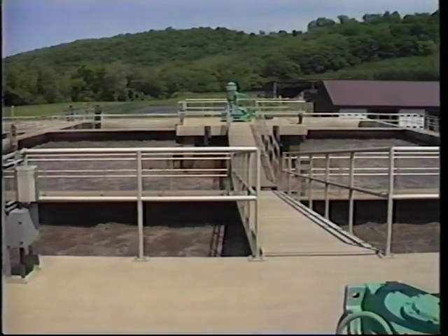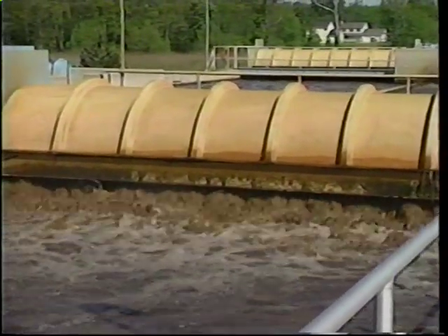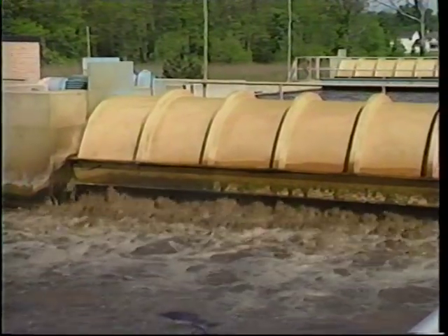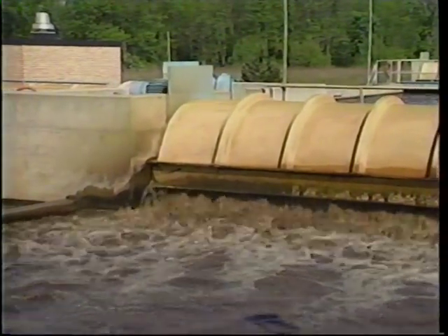stabilization mode. The oxidation ditch is another variation of the activated sludge process that is usually operated in the extended aeration mode. This system utilizes a continuous loop type of tank with a rotor. The rotor is a mechanical device that includes a shaft with many paddle-type blades on it. The purpose of the rotor is to mix the contents of the tank and to transfer dissolved oxygen into the